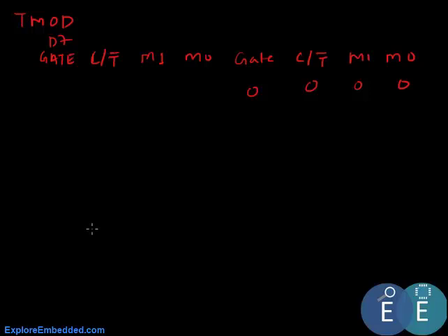So we know that if the timer makes 3 counts when it is used for UART, it generates the required baud rate. So we would hardly need anything more than 255, so it is used in 8-bit auto reload mode.